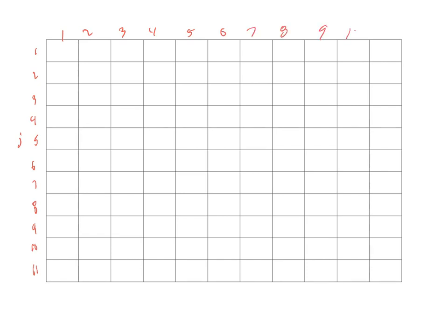So I know that if I'm in this column or this location here, I can look at the row and the column indicator, and I can say, well, I'm in row 1, comma 1, so I'm looking at the self-admittance, and I'm going to calculate and add up all the admittances for bus 1. And then if I'm in 1, 2, then I'm going to subtract the admittance between 1 and 2, etc. So now I would encourage you to pause the video and take a look at the positive and negative sequence diagrams. You may want to try to do those yourself and see what you get. But essentially, I'm going to go ahead and draw those or create those now.